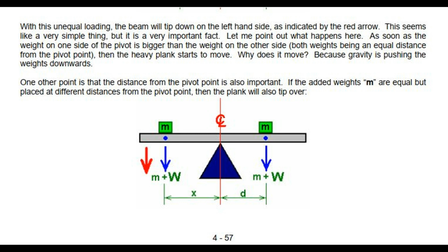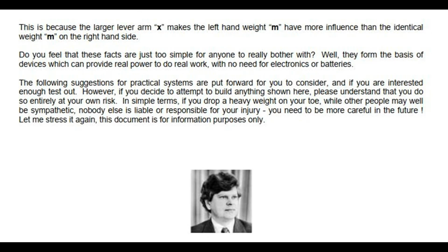One other point is that the distance from the pivot point is also important. If the added weights M are equal but placed at different distances from the pivot point, then the plank will also tip over. This is because the larger lever arm X makes the left-hand weight M have more influence than the identical weight M on the right-hand side.